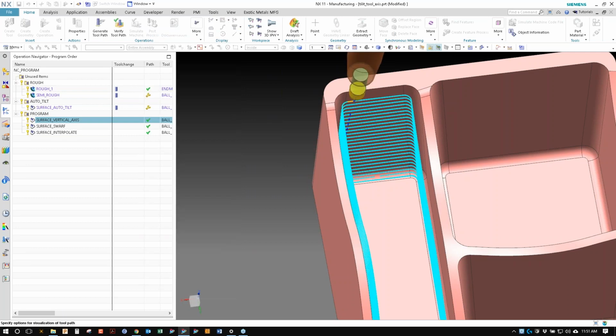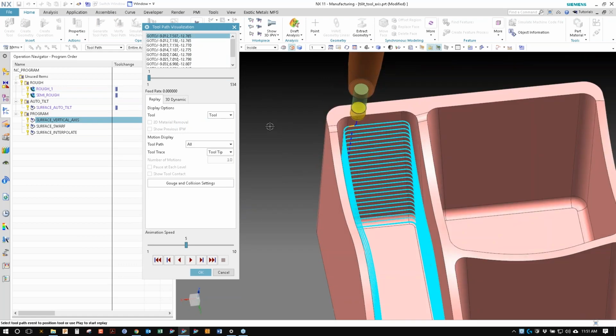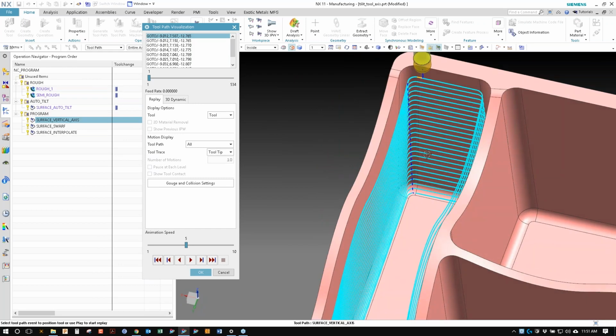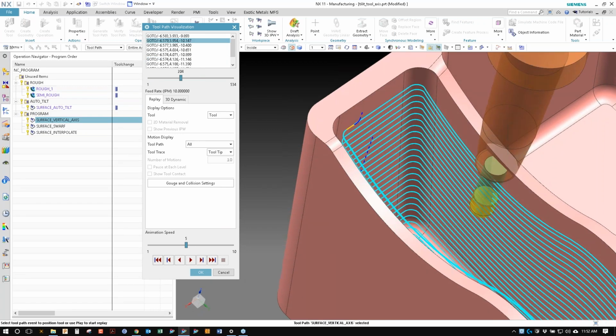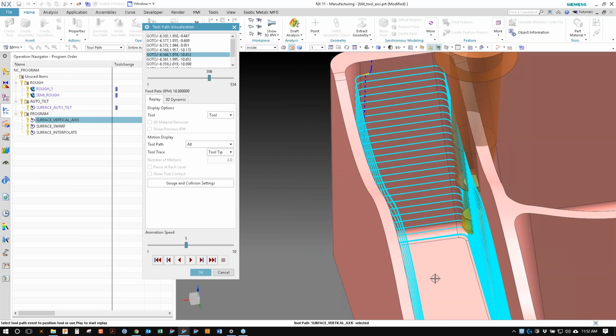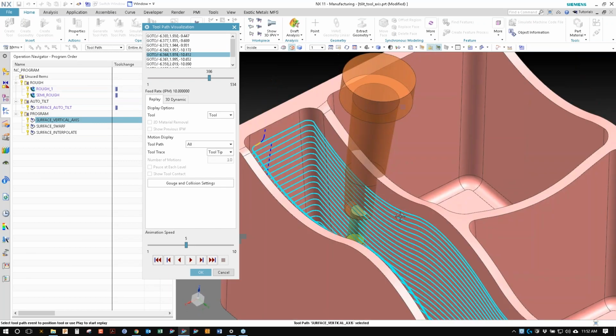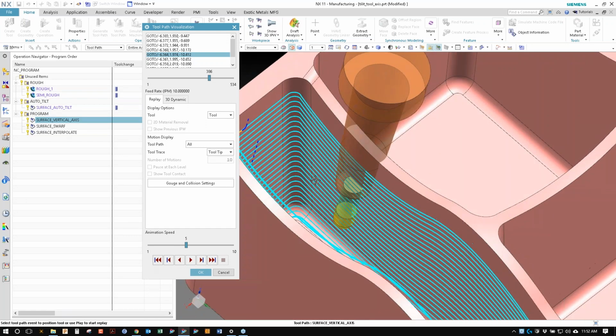So basically we have a toolpath that is 3-axis, and you can see here, based on only one set of I, J, and K, that it's 3-axis. And if I was to play through this, maybe in the undercut area, you can see that it's definitely colliding, cutting right through that wall, and the machine operator would definitely not like that, and probably the customer would be mad too.